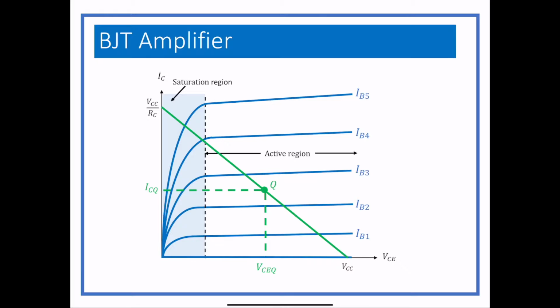So when we talk about amplifiers in general, we need to know what the transconductance value is. That is the parameter, well, there's one of two, but they're related. Transconductance or small signal AC resistance are going to be related to each other. But we want to split up the base emitter voltage into its DC and AC parts, just like we did with MOSFETs when we took the gate to source voltage.